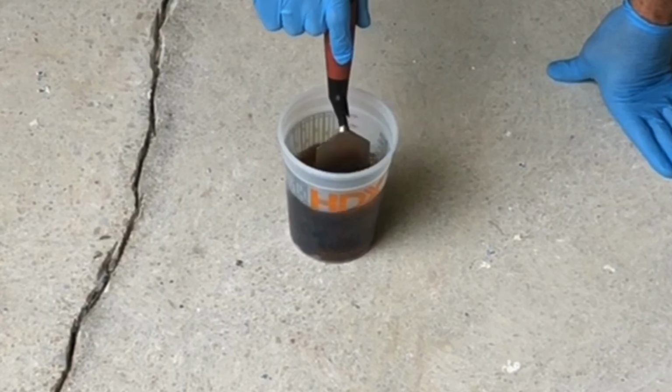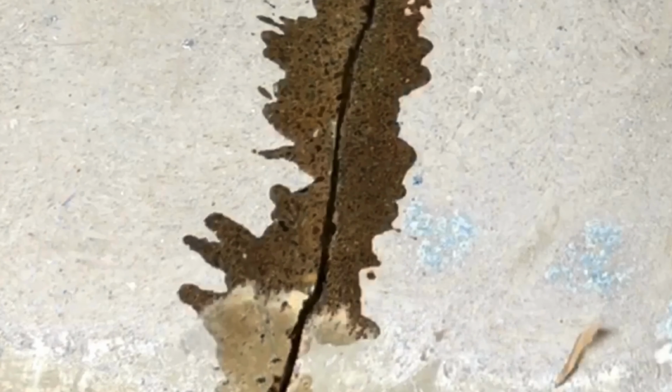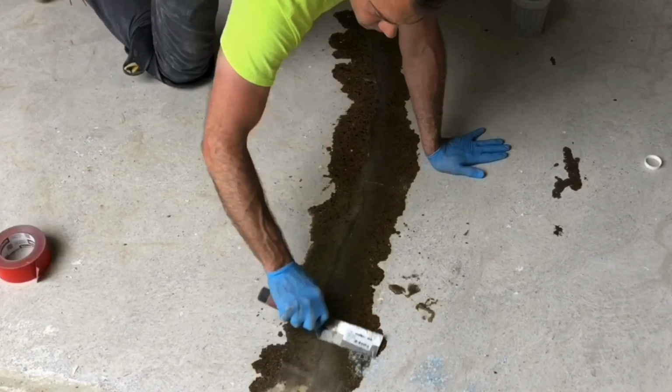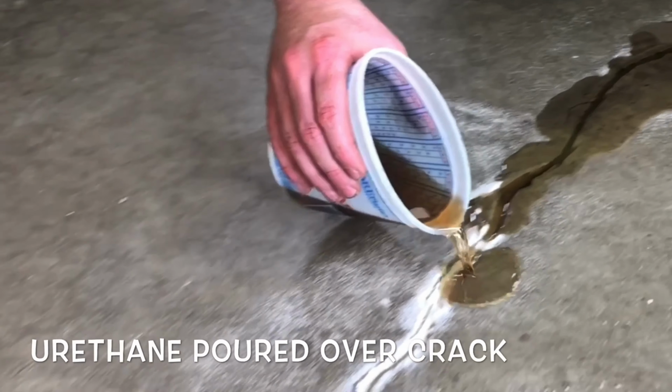that can soak in, and you'll never fully get all of those little micro cracks out, but you need something that can navigate those in a clean void. Think of it like a root structure where it soaks into those little pores, holes, and cavities, and then stitches it to both sides and anchors it properly to the concrete. So that would be something along the lines of a low viscosity repair material like a urethane or an epoxy that's typically designed for repairing bridge decks or some sort of suspended concrete decking system, where it can soak in and fuse back together relatively quickly, but also attain outstanding adhesion that's greater than the concrete itself.